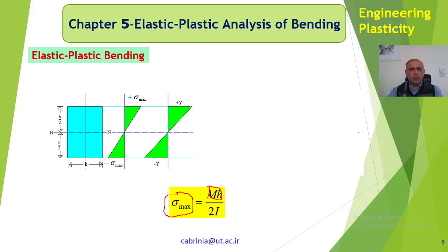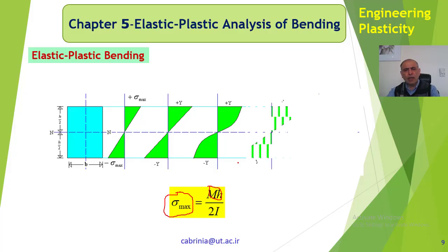So that is the ultimate point in the elastic part of the material. Okay, so if we take the load off, if we take this m off, then it will go back to 0. Okay, it will be 0 all over the place. But if we increase m further, then we go into the plastic region.